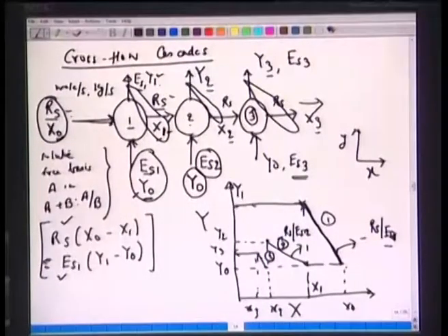And more importantly, say there is an equilibrium curve like this, and also important to note here is that this is very similar to what we had in the case of the continuous contact process. So in the continuous contact process also, if we have two streams flowing concurrently, and we give them enough residence time, then the leaving streams will also be in equilibrium. But it's a continuous contact process, so there we can assume the operating lines are continuous. Here, since we have stages, in one stage, two streams come in contact, they spend time, and the leaving streams are in equilibrium.